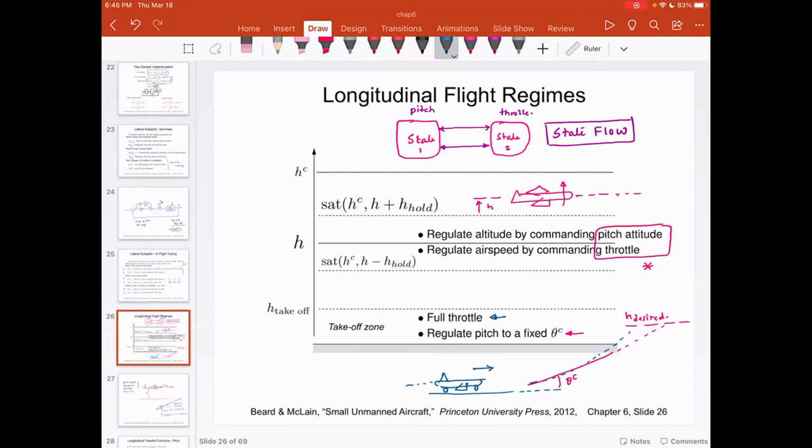You also want to note in what state the aircraft is, whether the aircraft is taking off, at constant level flight, or beyond the critical flight regime. You want to make sure that these transitions are done properly. And these transitions are achieved by means of something called a state machine or state flow.